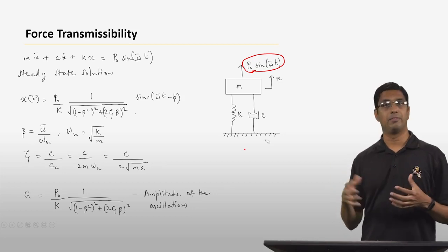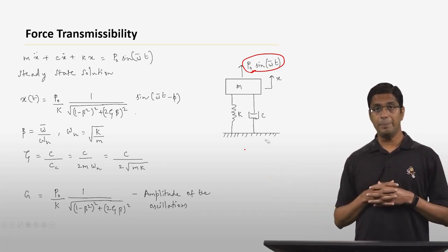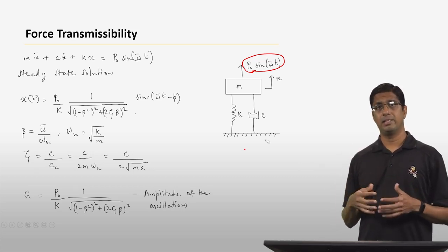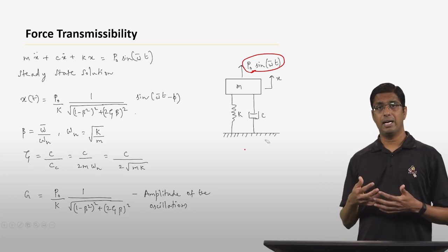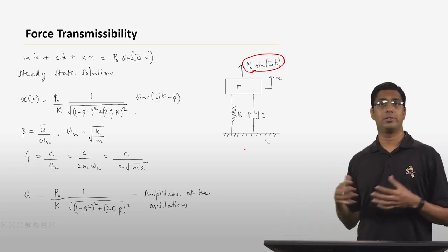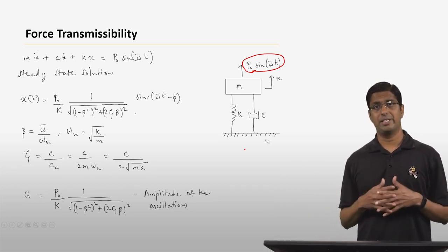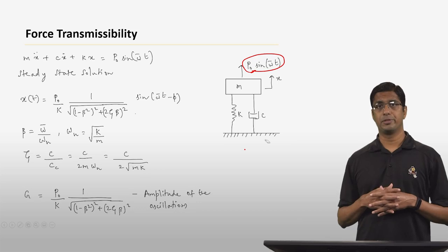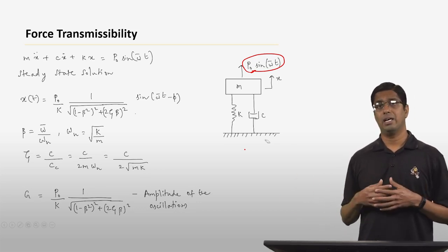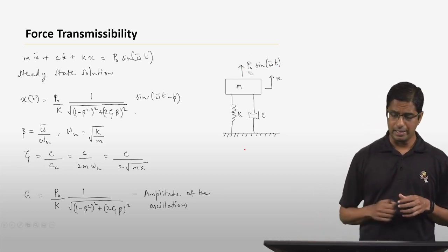You can think of a motor that is mounted on a base or on a beam, and if this motor has some kind of an imbalance, then it will undergo vibrations. The amount of force that is being conveyed to the base or to the beam on which it is mounted could be quite large. So we are interested in finding out the maximum forces that are transmitted to a foundation or a beam on which a particular machinery is being mounted. That is the reason why we are looking at this particular system.